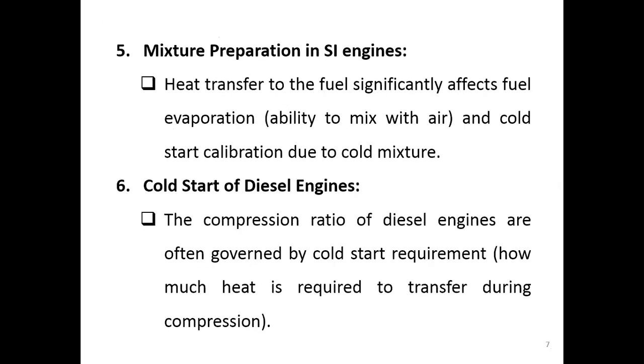Heat transfer also has an impact on the mixture preparation in the SI engine, because in the SI engine we mix the air and fuel together first. So the amount of heat that transfers to the fuel will significantly affect the fuel evaporation. If we have heat transfer to the fuel so that it evaporates, that means the fuel has the ability to mix with the air.